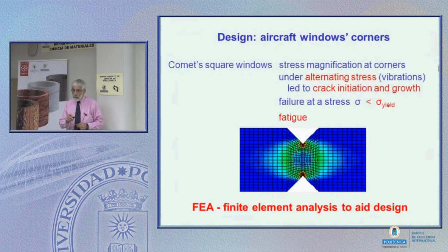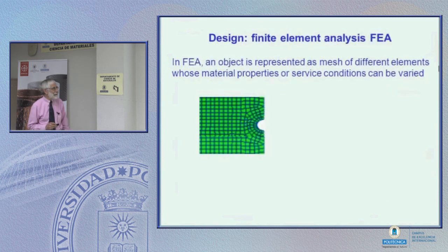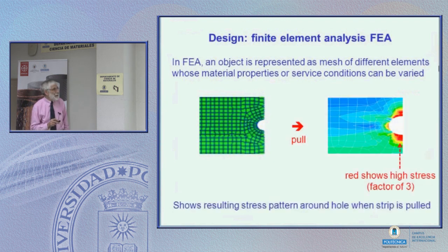So we learned a lot about fatigue. Or rather, we didn't, even that was before my time. But people learned a lot about fatigue. And of course, we are material scientists, we learn very quickly. Or do we? Because when you take something, this is again a finite element model, this is just half, it has a round hole. And when you pull it, you see the stress is about 3 times here than it is on the area here. So a round hole looks innocent, it looks simple, but even here, the stress is 3 times as great.